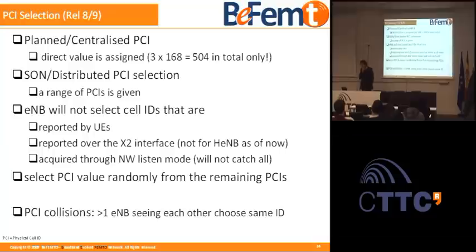It's all good, you know, your UMTS network may just do well, LTE maybe as well, but as you start introducing femtocells, you get very quickly into collision, actually. So you may assign the very same PCI to nodes which are in a neighboring relationship, and this is causing a lot of problems for mainly the mobile terminal, because it doesn't know where to go, essentially. You know, it has a PCI which is the same.